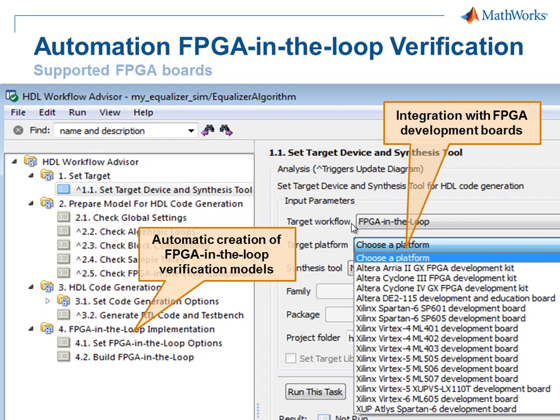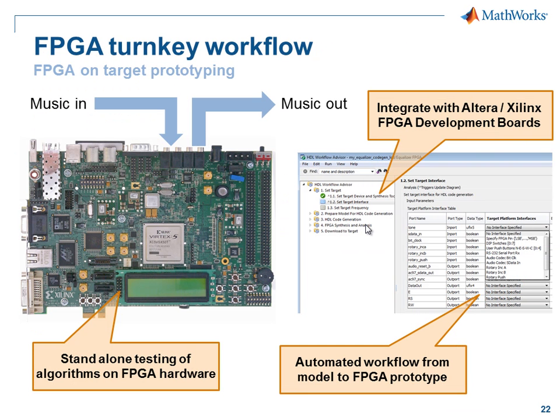So it's not just that we want to give you the capability to perform FPGA in the loop, we also want to make it easier for you to actually use these kind of capabilities by automating the process of creating these kind of verification models. This is a workflow which works together with HDL Coder. However, we also provide you with wizards to get to the same results for handwritten code.